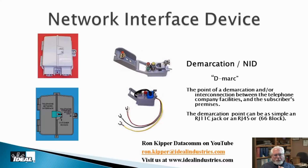So you look for this gray-looking box, and from this box, you are going to pull cable into typically a low-voltage panel of some sort in the building, and from there we'll home-run wire out to all the different phone jacks we're going to install in the building. And as a general rule, I tell everybody, make sure you don't leave your cables exposed on the outside of buildings. Hide it if at all possible, or put it in conduit to make sure it doesn't get damaged, because things happen, so to speak.